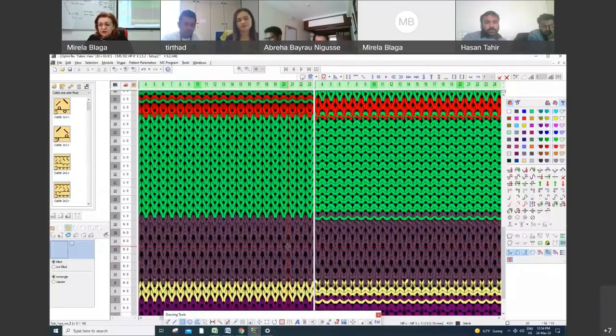In case you study comfort, there is a property named porosity of the fabric, which directly influences moisture management, for example. Yes, stitch density, porosity, air permeability, moisture transportation rate, and some perception of the comfort level. There were also some strength-related properties, but that was not the main focus. The main focus was the comfort level.